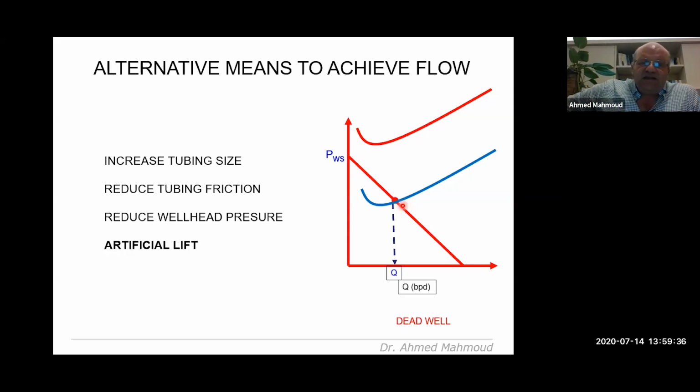But if we take the most common method, let's say the continuous gas lift system, the time between one valve to open and the second valve to open is time related, but the ball is in your hand because you are the one in control of the gas being injected, the rate and the pressure of the gas being injected.